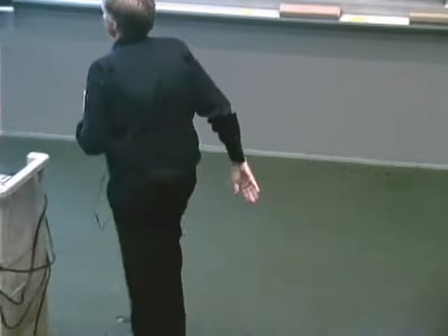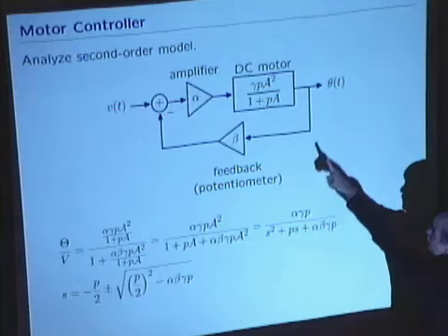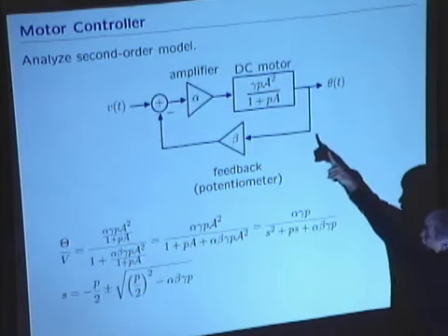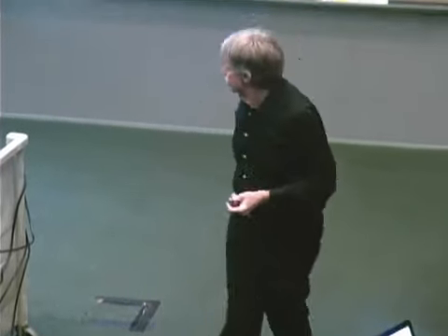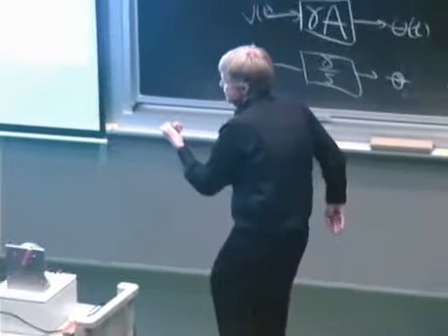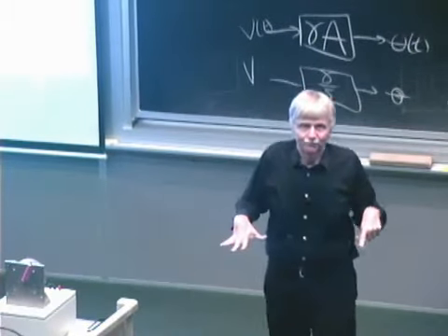That's just math. That's the math that was shown over here. All I did was write the second model up there, figure out the system function, find the poles of the system function. They depend on beta. That dependence is shown here. And so the response then, that's where the oscillations come from. If the gain is big enough, I get a pair of poles that are off the real axis. The fact that the poles have an imaginary component means that there's an oscillation.